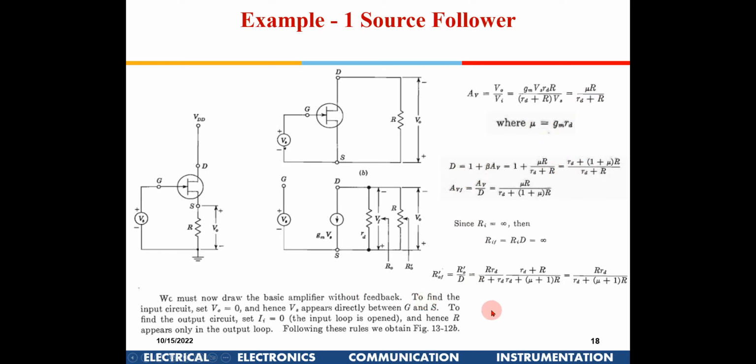Sir, the resistance and your input is connected to the ground. How is your output signal going to the gate? See, from this output signal, along with the input signal, the input signal minus the output signal is available to the gate to source.